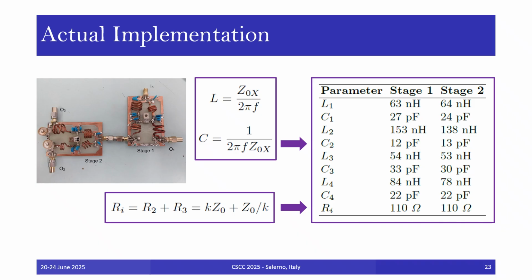High-frequency thin-film high-power chip resistors were employed for RI of both stages. Thin-film chip resistors were used because they feature low parasitic effects, particularly low unwanted inductance and capacitance, thus limiting performance degradation above tens or hundreds of megahertz.